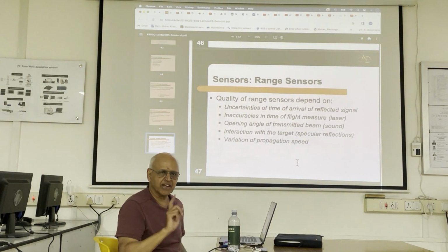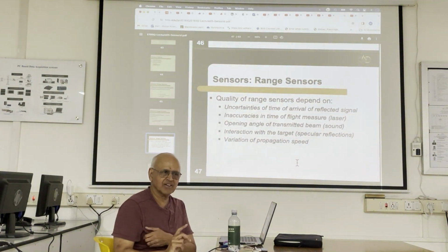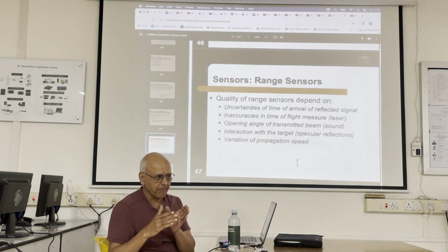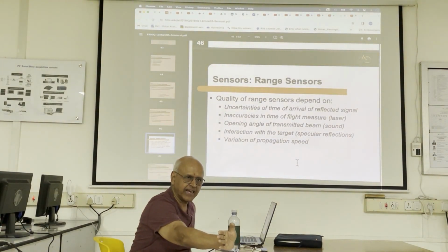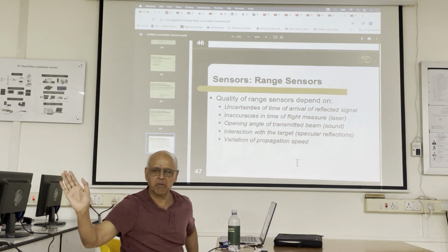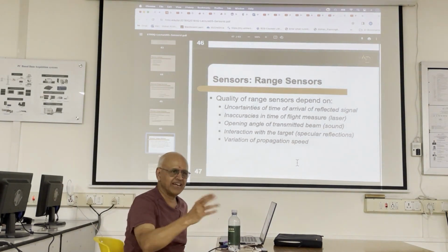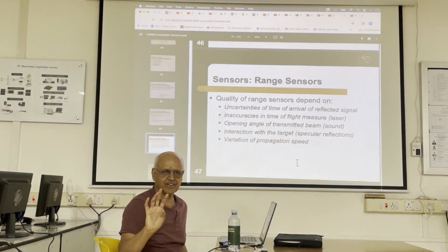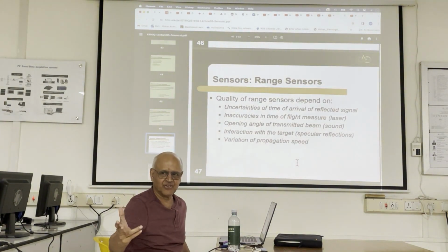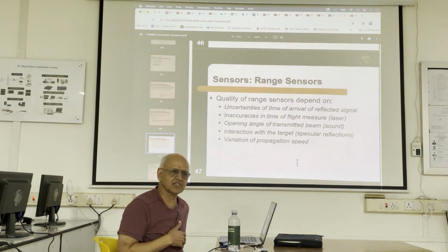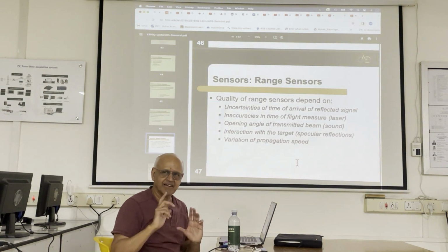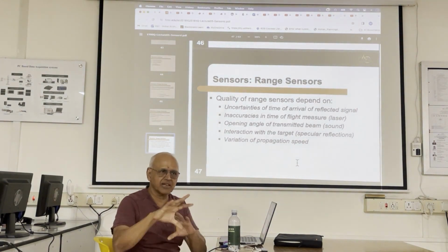So sonar has this particular problem, LiDAR too, right? When you approach an obstacle from an acute angle, it'll bounce off and you won't get anything coming back to the receiver, right? So you think there's nothing there, and I've seen robots hit that. LiDAR can also have the same problem with glass surfaces. For some reason, you don't get a return pickup for certain kinds of surfaces.